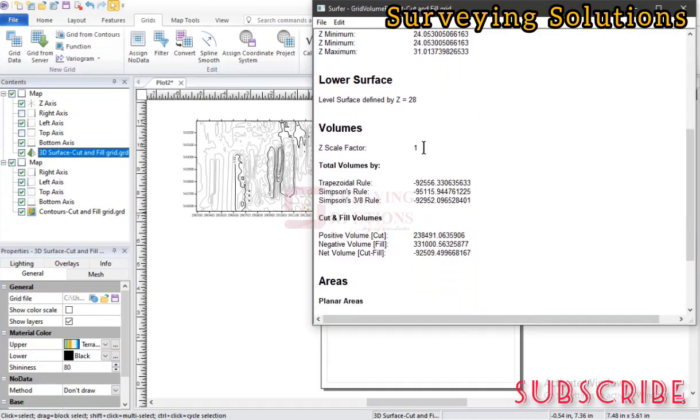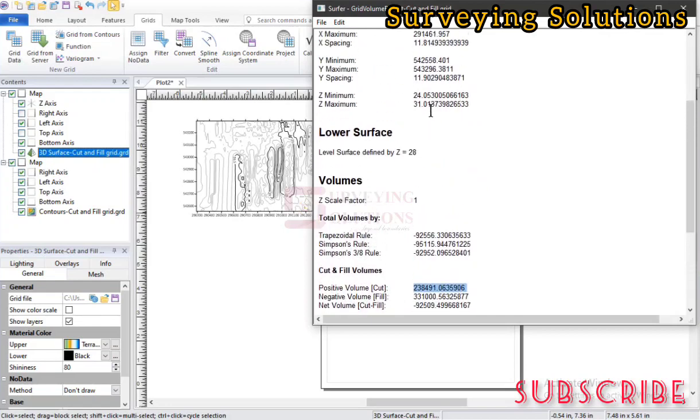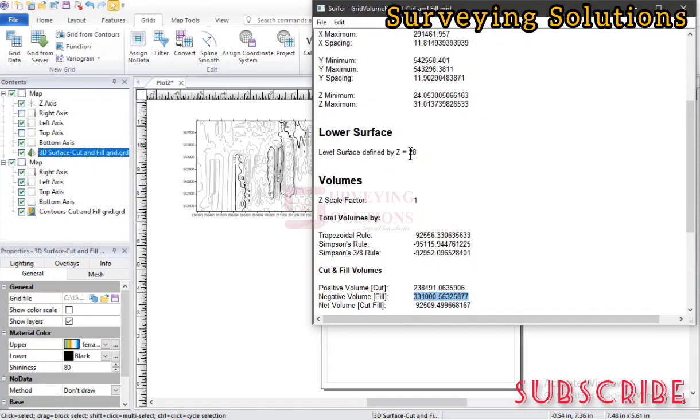Good. So we are now going to come down to the volume section and look at the cut and fill volume. This means that we are going to cut this amount of volume from the highest Z value on the first surface down to 28, and we are going to fill this amount of volume from the two surfaces to get to 28, right?